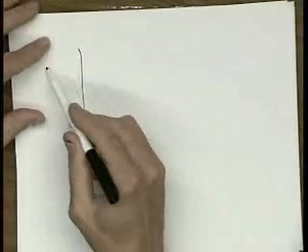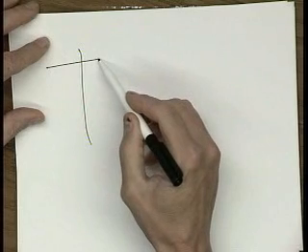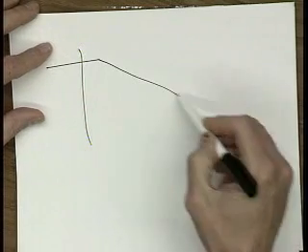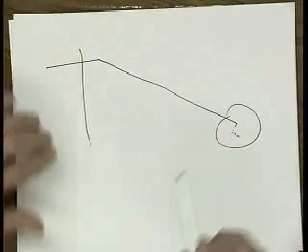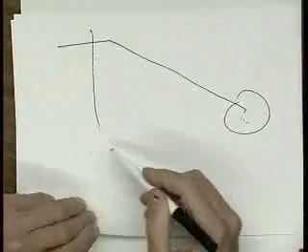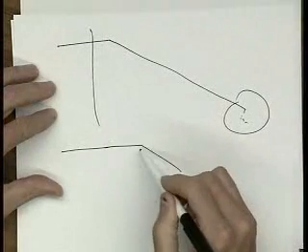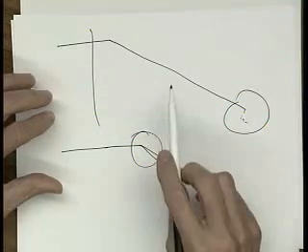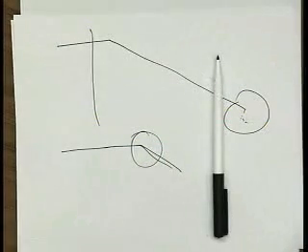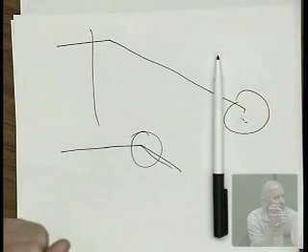And usually what happens is this, and here's the real problem. A good design will look like this. You'll have one very low frequency pole, and then a whole bunch of poles at the next spot. A good design will be where all the poles are kind of lumped together. Why is that? Because what's going to happen is this. As you look across your circuit, you will find, wow, this pole is really low frequency. So you'll go in there and fix that pole up.